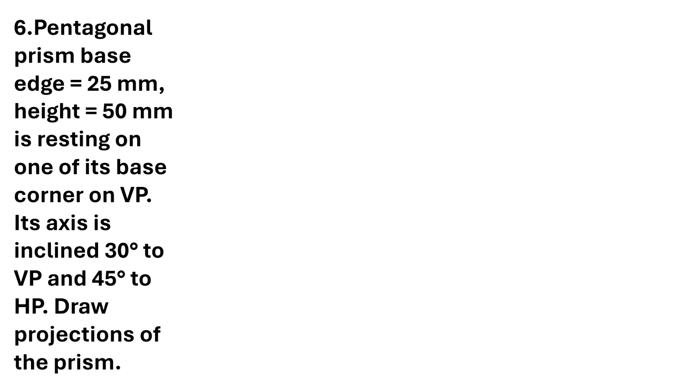Next we will solve the sixth problem in the worksheet. Pentagonal prism, base edge 25 mm, height 50 mm, is resting on one of its base corners on VP. Its axis is inclined 30 degrees to VP and 45 degrees to HP. Draw projections of the prism.